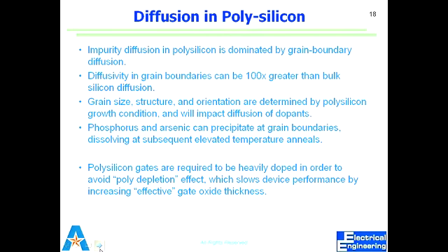Right? So then one can ask, okay, before this we could have said, which I was wondering, but nobody asked that, okay, if we dope silicon too high, mobility goes down. What about polysilicon? It's not a bulk mobility that matters now, because these are different grains. There are many more boundaries which can have many more charge carriers and interference. Now charge carriers don't have to pass through the bulk, and they travel on the surface.